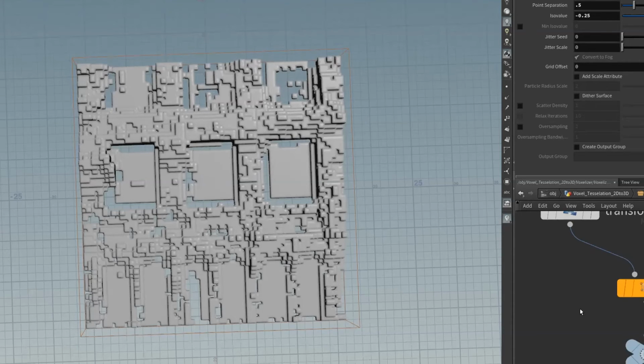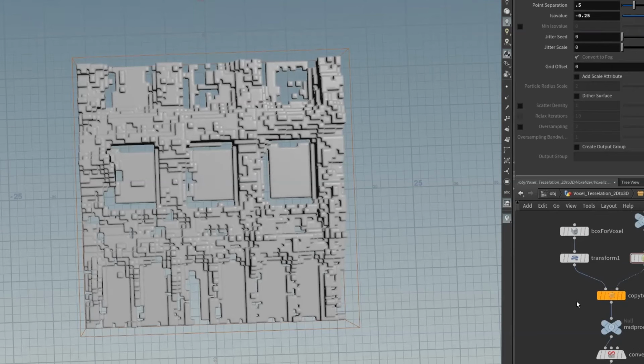Let's say you're doing a residential project, yeah, probably then you can use a really high mesh resolution. But if you're designing, let's say, a skyscraper, do you want that high detail? Because what you would probably do at the end is render the whole building from the outside, very far away. So you don't want that much resolution.